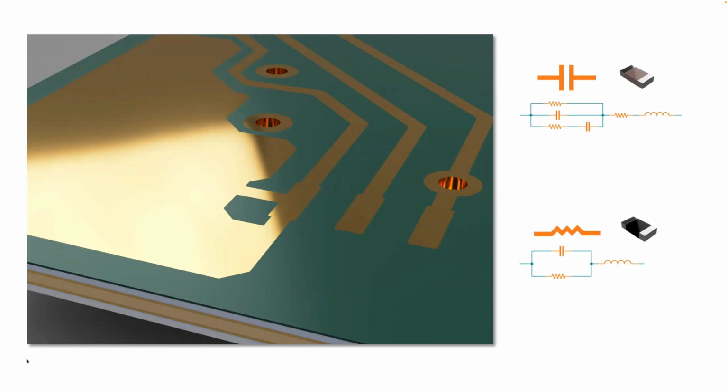Signal integrity is factoring the board into the equation. And going back to the comment I was making earlier, this difference between geometry and circuit analysis: did you capture mutual inductance, lead inductance, the various stack-up of the board? The image on the left shows a simple 4-layer board stack-up. In that four-layer stack-up, I can guarantee that the size of the plate that is the internal plane is bigger than the size of the plate in any capacitor you have on the PCB.